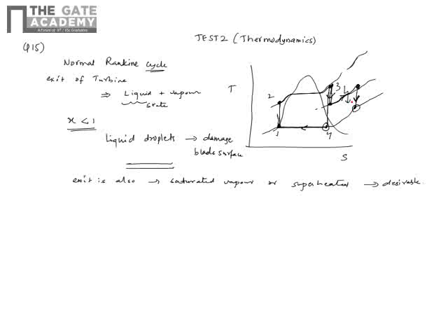So reduced moisture content in the lower pressure side of the turbine is the option. Well, this increases the work done, but increased maximum temperature I would not say, because you can again reheat to the same temperature as at the exit of the boiler. So B is not the option. Reduce load on the condenser?